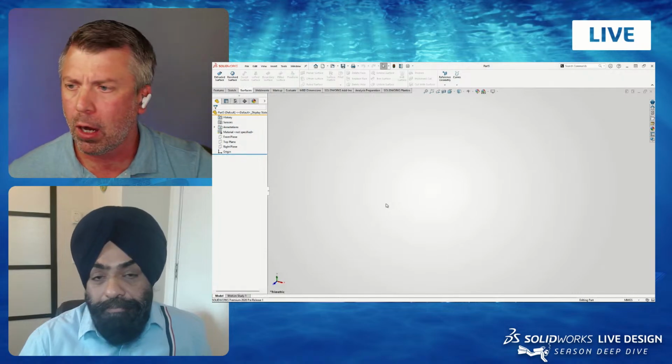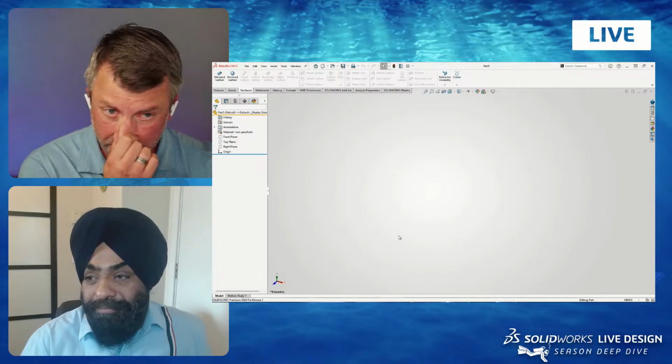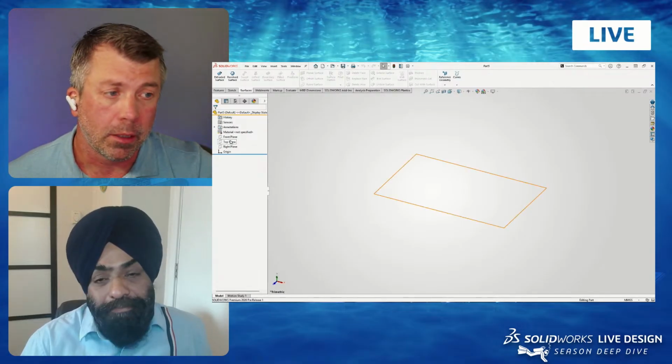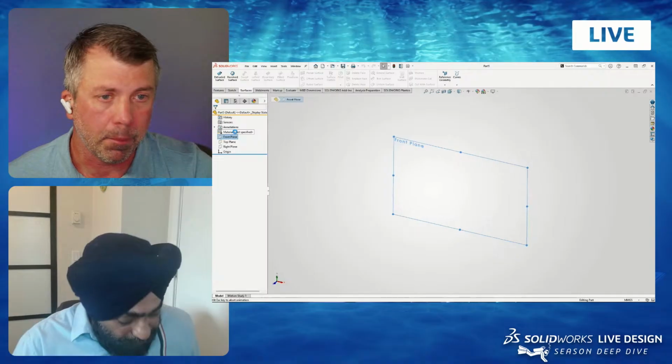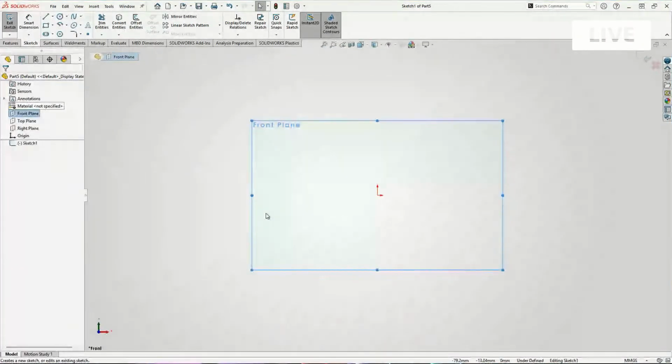Yeah. All right. So let's go in. My next example was getting into some fun equations. This one's pretty quick. I can make it quick, but another way you can drive your sketches is by using basic equations as a parametric true equation versus imported data points. So the wing was an imported set of data points. SolidWorks did the job of connecting those with a nice spline, and we leveraged that.